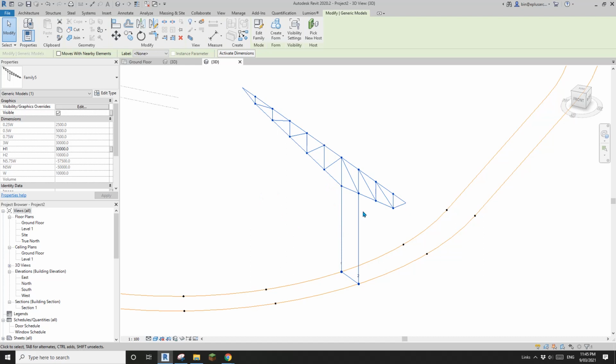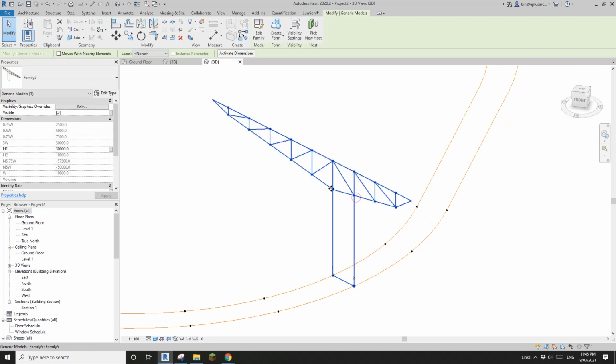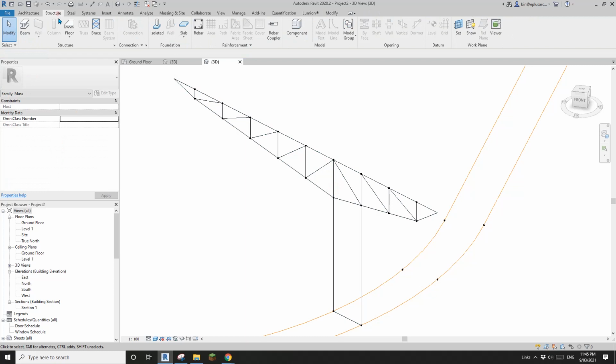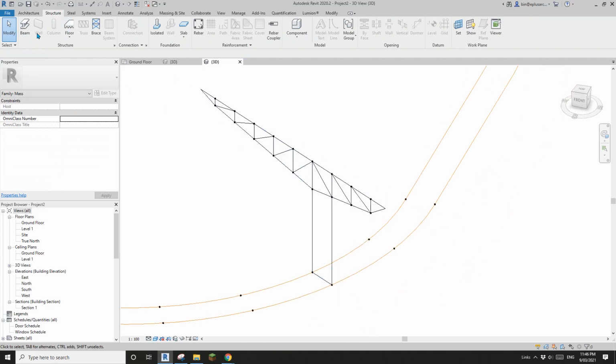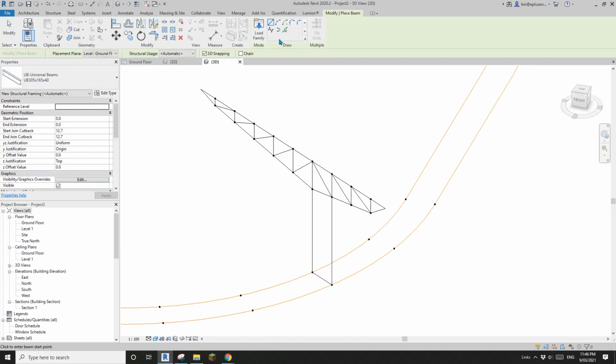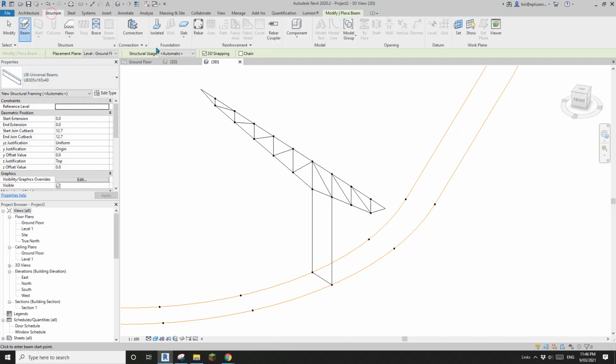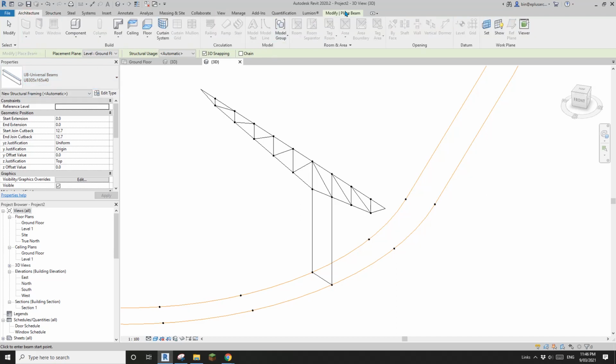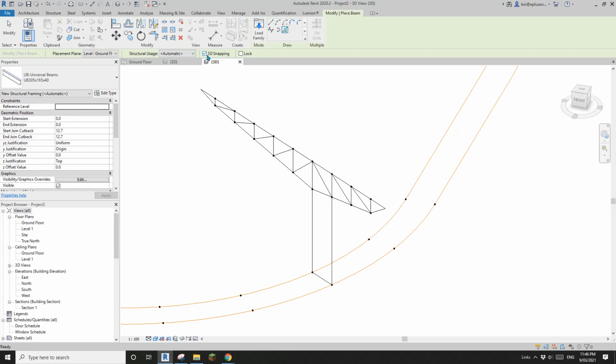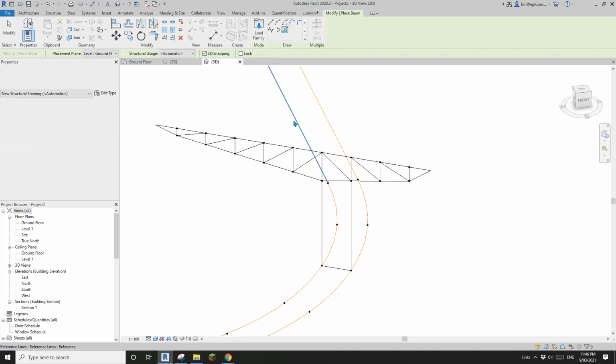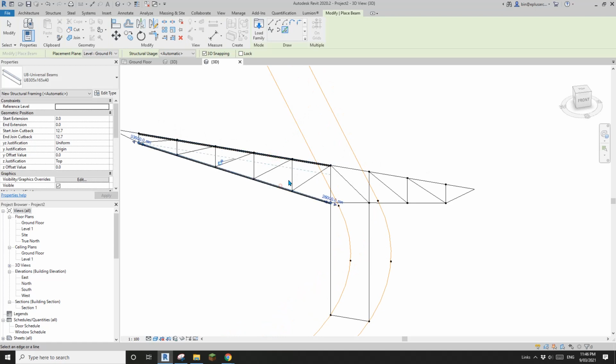So of course these are just lines, okay, and if you do a render you won't see them. And actually you can manually place. So see, if you create a beam you can manually place. If you have this 3D snapping checked, you can just place on these lines.